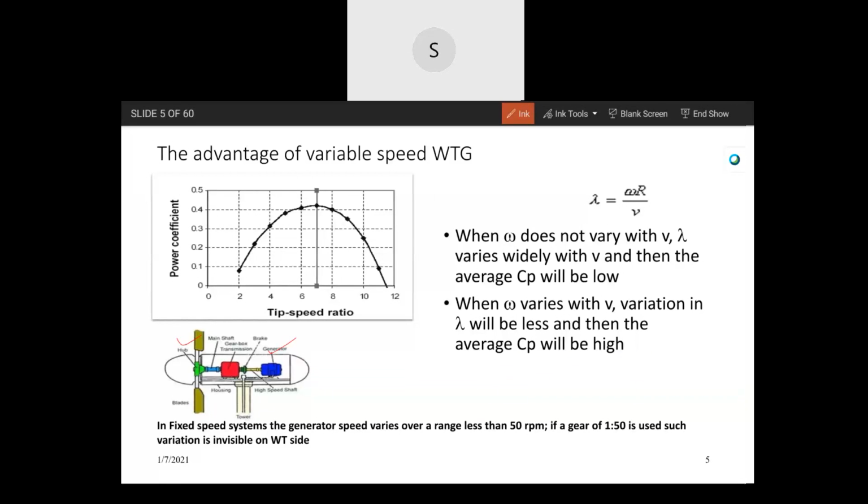The slip-torque characteristic of an induction machine shows that corresponding to a torque there is a fixed slip. And the slip means a speed, that omega, the angular speed, and the torque together make the power. That means for the electrical machine, the speed decides at what power it is to operate.